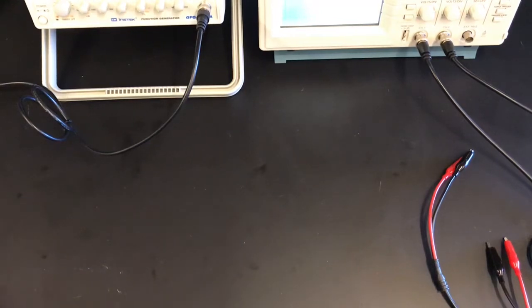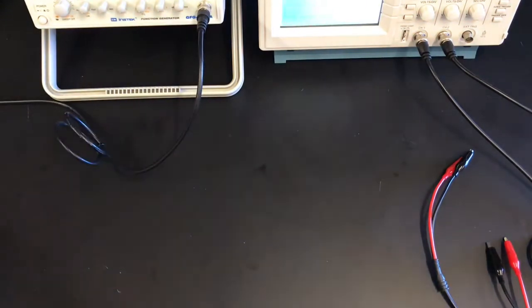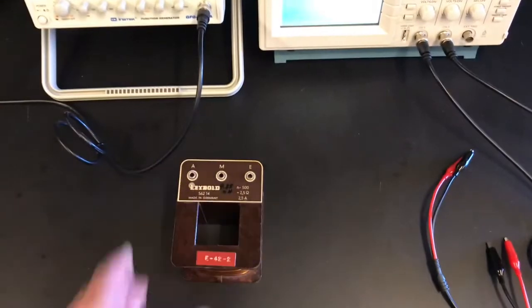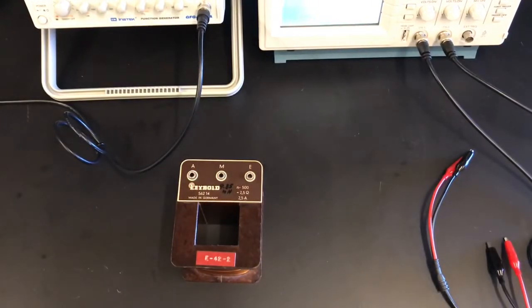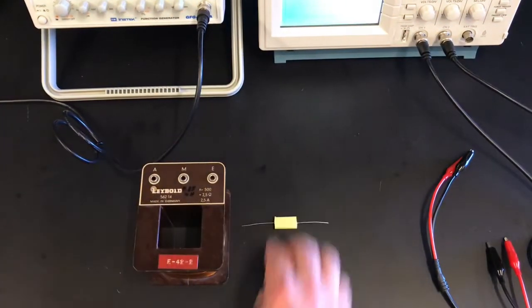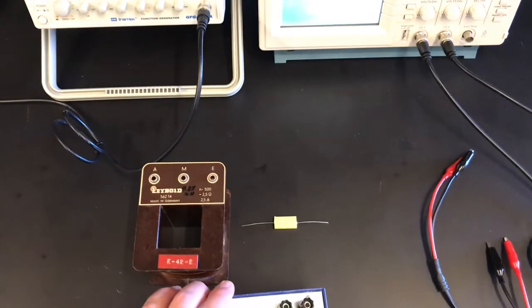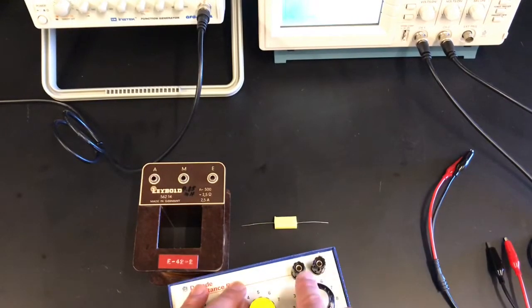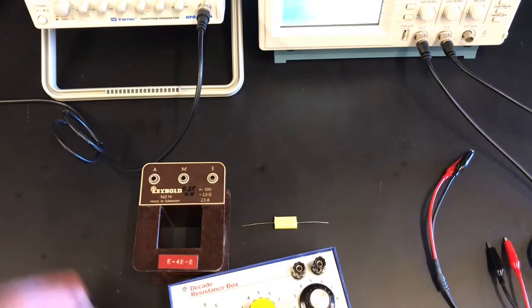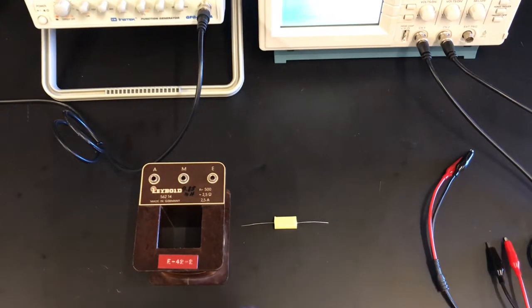All right, we're going to set up an RLC circuit today, and if you look at the lab handout on page 2, the circuit that we're setting up, we're going to take the output from the function generator here and run it first into an inductor, from there into a capacitor, and then finally into this resistance box, and then back, and then we'll have the oscilloscope channel.